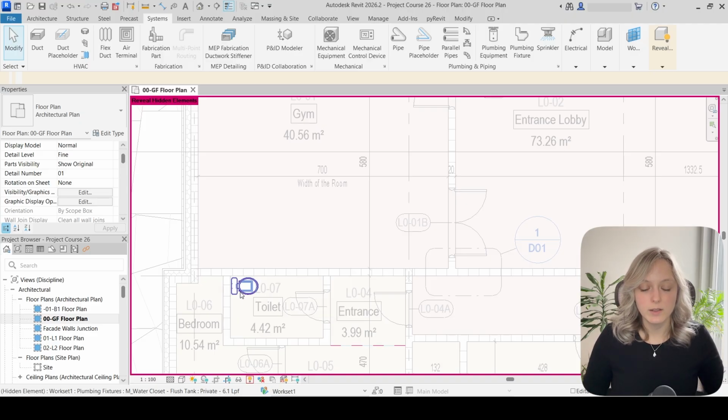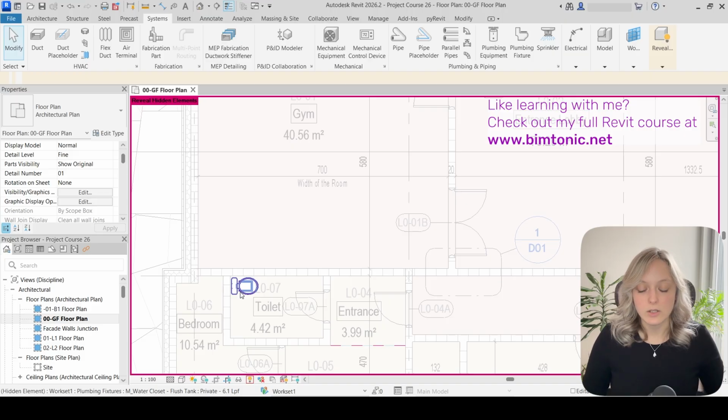And when you hide something this way, it basically disappears only on this plan. So sometimes you can create a section or some elevation or some 3D view and then have this element pop up in your drawings. And that, at least in my case, when working on bigger teams, has proven to be very big trouble because sometimes people will not be cautious enough and they will hide things this way, and then other members of the project will not know of this, and then they will have a lot of trouble with some elements appearing in some other views, and that is obviously not good.